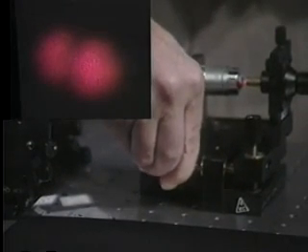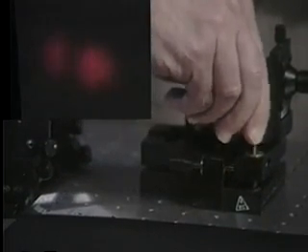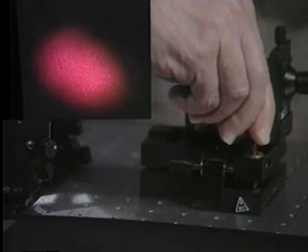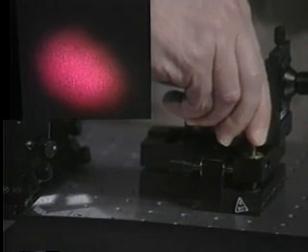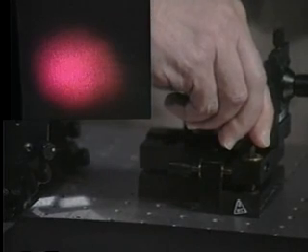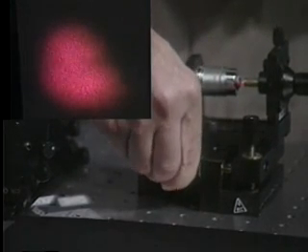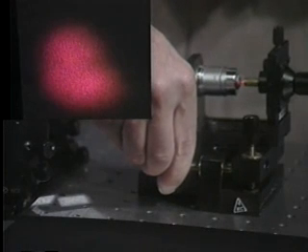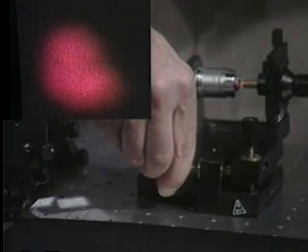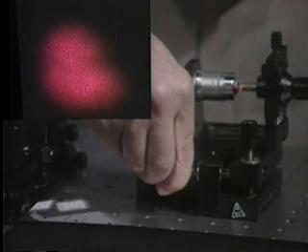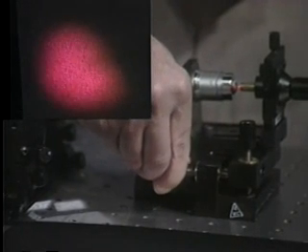You can see this one here. You get a nice dark line in the middle, and then if I align it over here, you can see it's blobby. It's a mixture of modes. That's why you don't see a sharp dark line in the middle, but you get a mixture of modes. Remember, in the other one, no matter what I did in the alignment, it was still single mode coming out, just one lobe coming out.